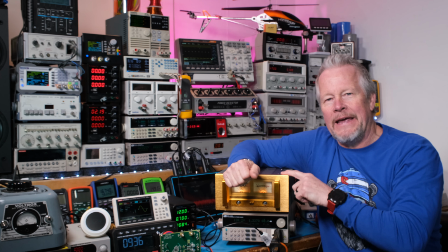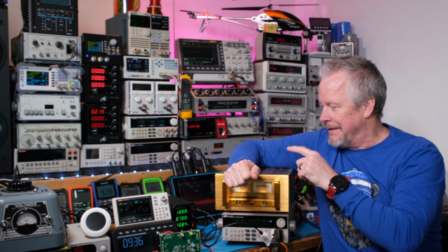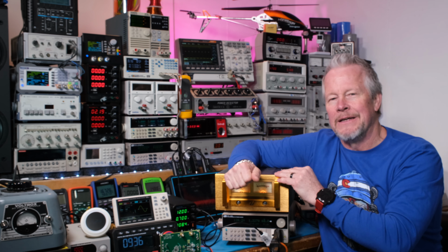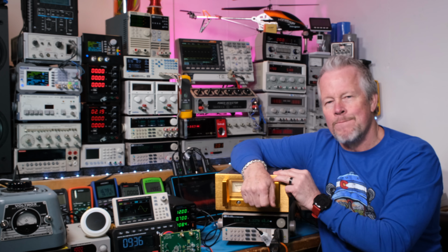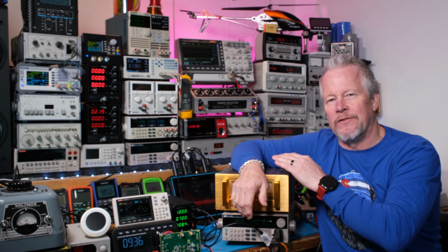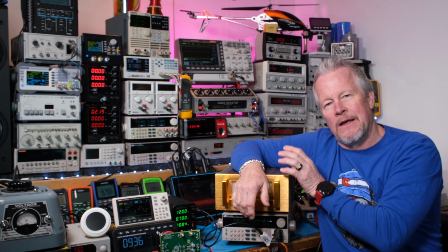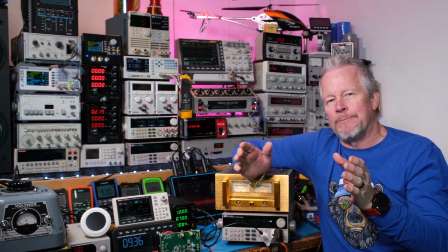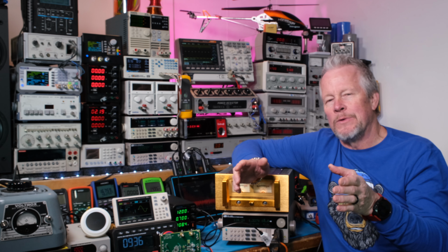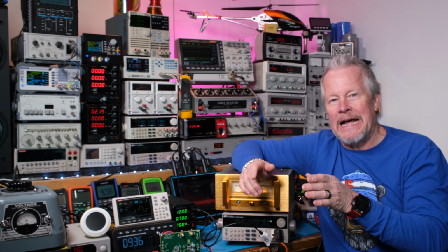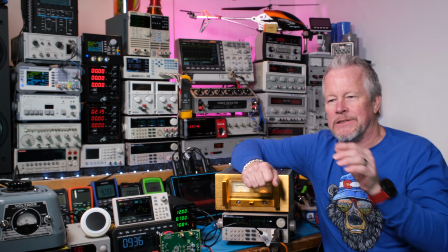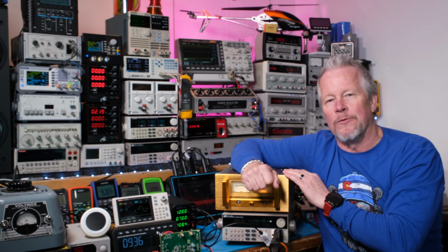Now, today, if you're still with me, what we do is active power factor correction. Now the first stage, instead of that just being a simple bridge rectifier, is a PFC stage. So we try to keep that current in a bunch of little smaller pulses, lots of them, so that it's easy to average with the capacitor to make it look like a sine wave.